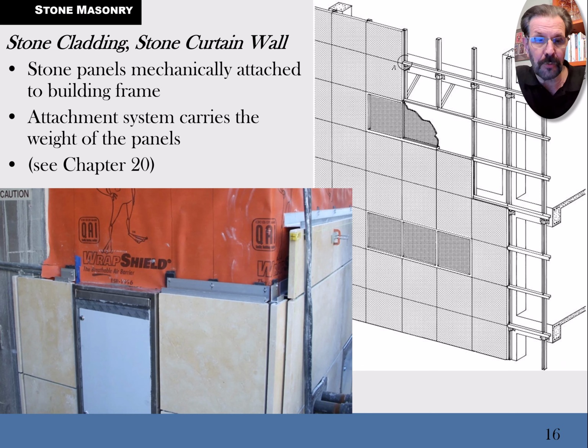They end up with a cavity wall, a cavity behind the panels, so that any moisture that condenses behind there can weep out, just like you would behind a brick veneer wall around a typical house, where you've got a cavity in there too. It's done in a similar way, and the angle iron is purposely set up the way that it is, where the leg is down at the bottom, so that there's no place for water to collect and it can dribble out and that sort of thing. It's all about shedding the water back out and still having a nice durable surface here.